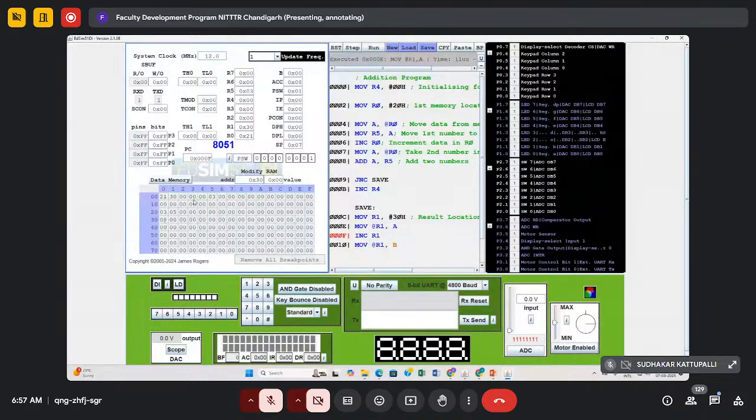I did an indirect, that made things a bit complicated, but let's move the code. I could have directly mentioned the address as well, but I wanted to do indirect addressing. Instead of that, you can write directly 30H, it will go to that location. I just wanted to go through it. If we are comfortable with this, we obviously will be comfortable with that as well.